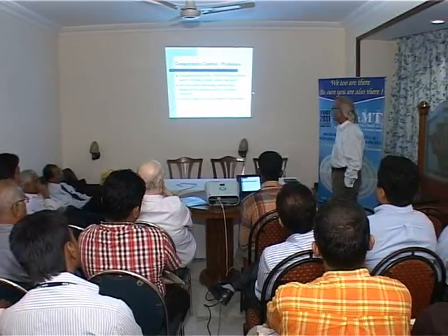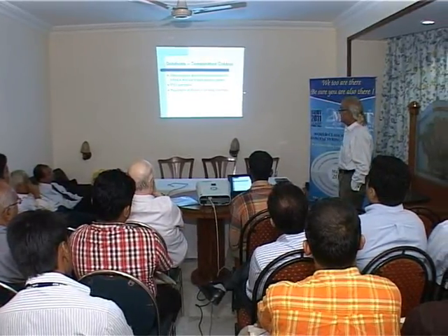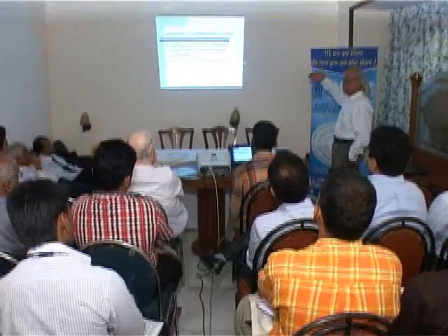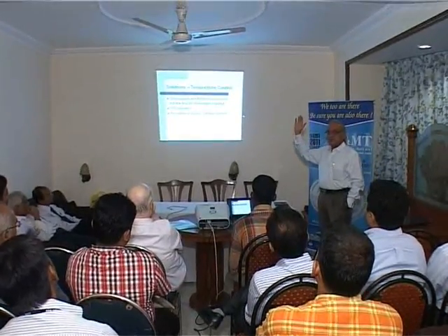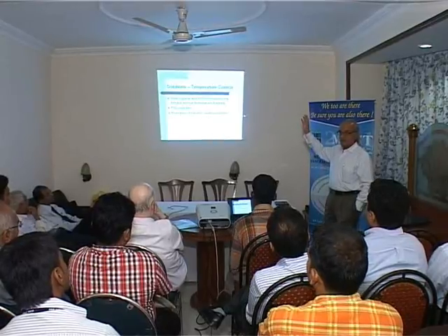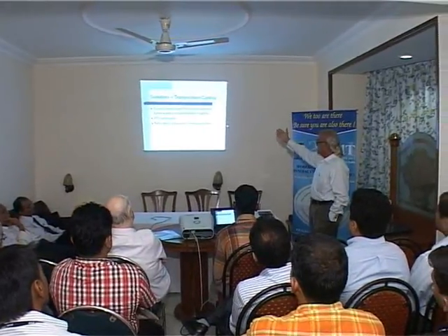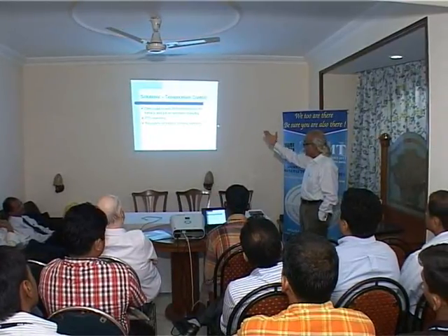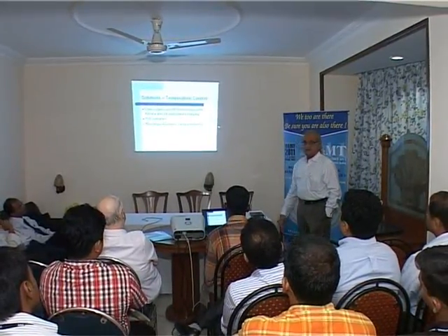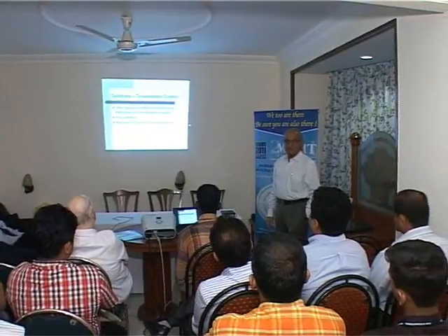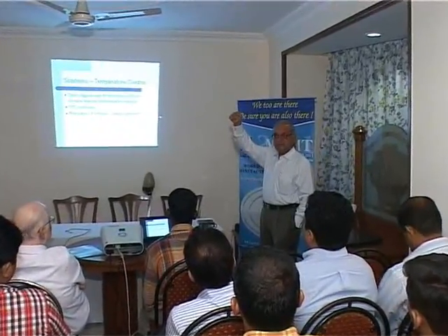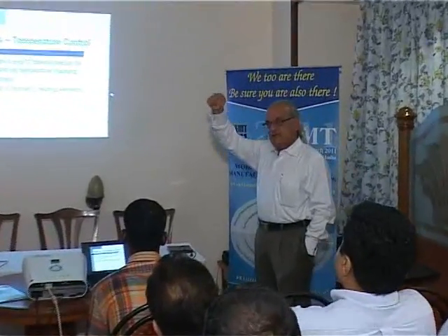Next. These are all add-ons. You buy one pair of shoes, you get one pair of socks free, kind of thing. So, all kinds of these instruments. And the first item, what we call mapping, furnace temperature. You have a thermocouple in the furnace. It is faithfully measuring the temperature. But are you sure that temperature, with reference to the job, is reaching the job?